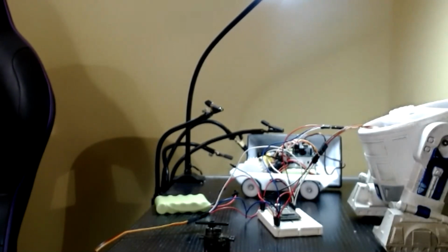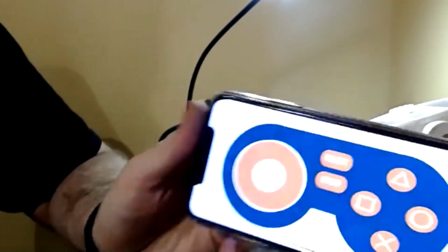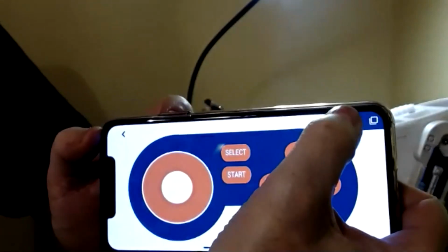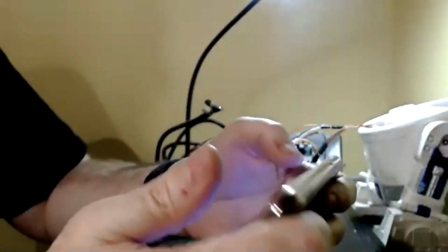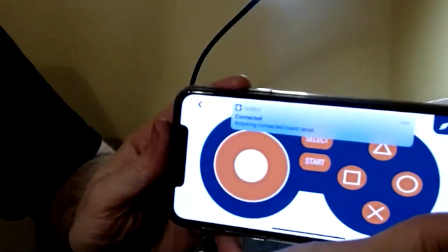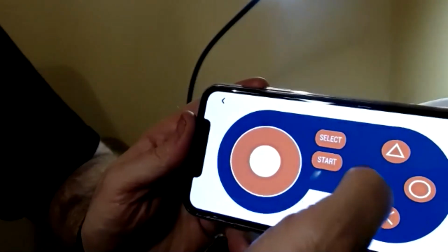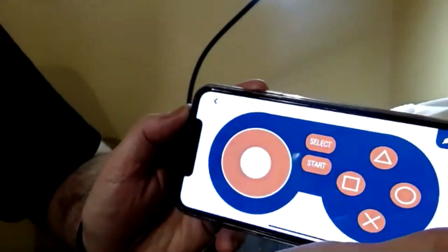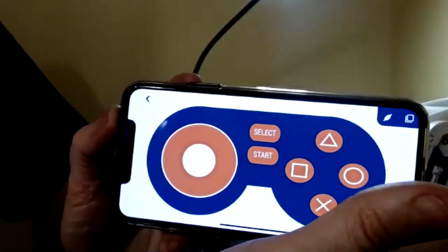So I've just uploaded the code to that Nano. And what you've got on the app there is a little button that looks like a plug. You press the plug button. It gives you a list of Bluetooth devices. You select DSD Tech, which is what comes up on the actual Dabble software. It's what the Bluetooth calls itself, and that plug is now connected. And that's literally it.